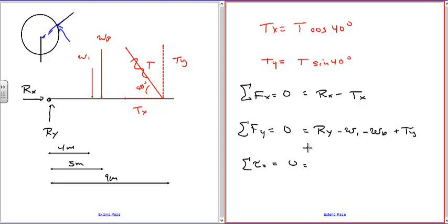So what we're going to have is 4 meters. I'll put in the weights first, and then we'll plug them in in a second. The distance from this point of rotation to the only mass, the point mass, is 4 meters times W1, and because this would cause a clockwise rotation, it's negative. This one also causes a clockwise rotation about this point, so it's also negative. That's 5 meters times the weight of the beam.